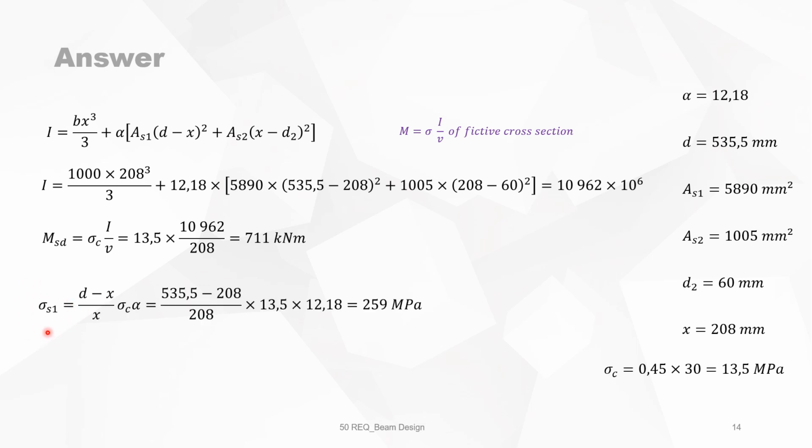We check the stress in the tension reinforcement. It gives you 259 megapascal. It's smaller than 400, so that's fine. The same, we calculate the stress in the compression reinforcement, and we have 177, which is fine.